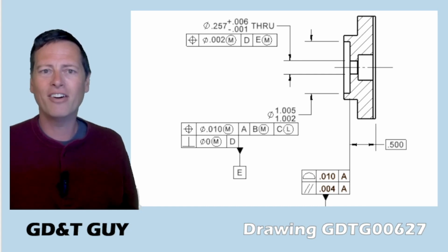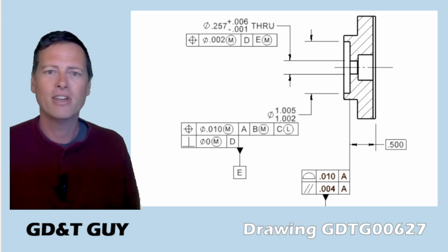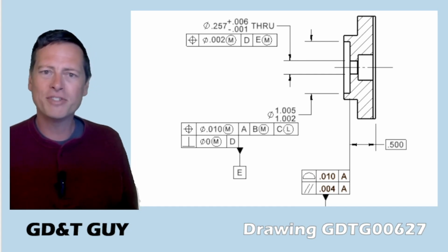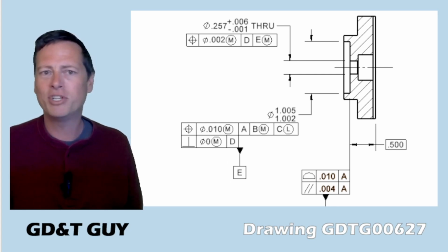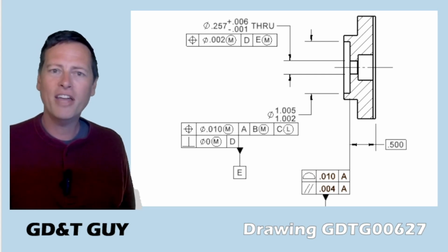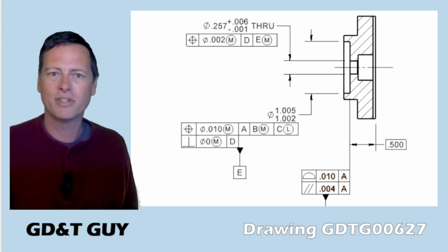Really pretty often, LMC and LMB are about preserving section thickness. So in this case, the wider the part gets, the looser is the hole position, but it happens in a one-to-one sort of way in which you preserve this section thickness. And it goes the other way too, where the narrower this part gets, the tighter the hole position requirement becomes.